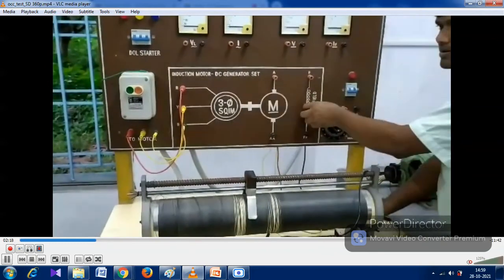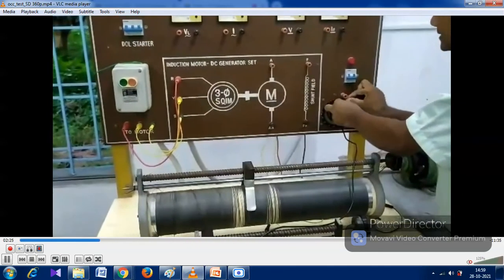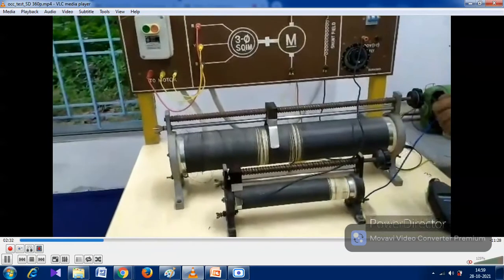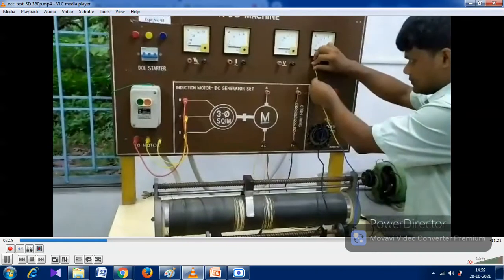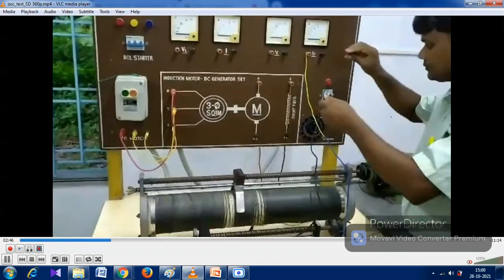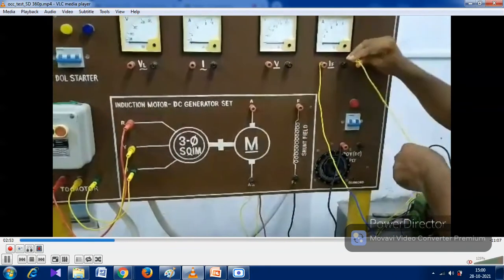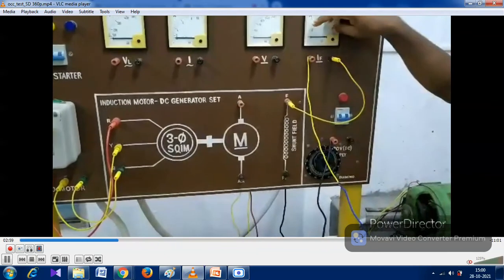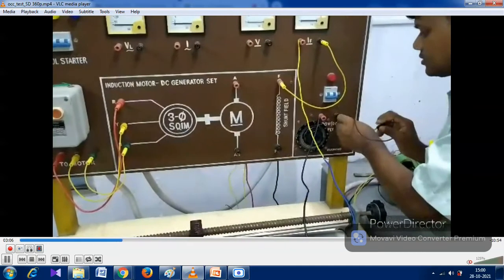This is the armature circuit, and the next one is the field circuit, and we have to control the current of the field circuit. So first we are making the field circuit. We are saying that this is a separately excited generator. First we take the separately excited generator, because you can easily control its field current, then we see how to do it on a shunt generator. Actually, first we are making the connection diagram.